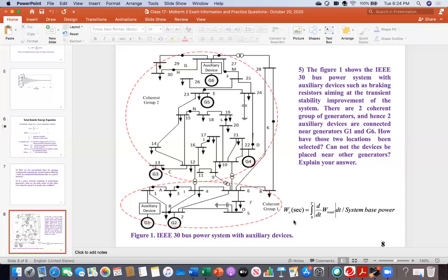And then you calculate the WC with respect to the fault for each and every generator terminal bus. For example, you assume that the fault is nearby that generator and look at the effect on all generators. You consider one fault at a time, but you analyze assuming that there is a fault at each and every generator terminal. And then you look at these numbers, these indices, WC. So where is the WC value the highest: at G3, or G4, or G5, or G6?